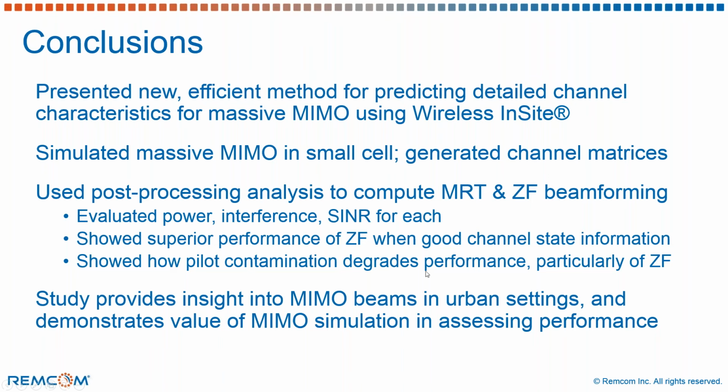In this particular case, zero forcing was much superior when there was good channel state information, but when we introduced pilot contamination, it had a severe effect on that performance. This study has demonstrated the MIMO capability, and it provides some insight not only into what MIMO beams look like in a complex urban setting with a lot of multipath, but it also shows the kinds of things that you can look at when you have a good MIMO simulation capability to help you assess beamforming solutions.